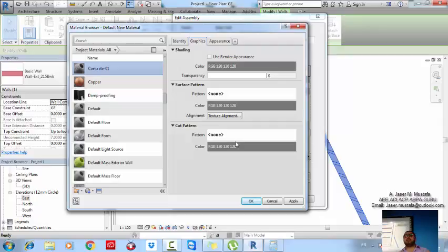And let me ask you something. When do you need to show the surface pattern? Elevation. What is the material that needs a surface pattern? The most important material to show the surface pattern, okay, it's the finish, but what type of finishes? No, curtain wall is something else. I will talk about it. The stone, which has the rows, the block work has rows. Those are the two materials that you need to show the surface pattern. But you are not showing the plaster surface pattern when you are submitting. Usually you don't show that. Fine?